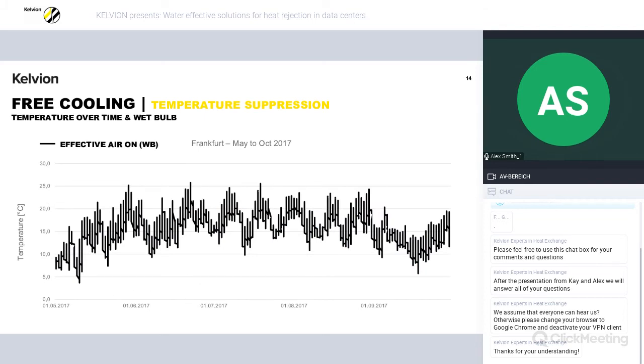If we're able to reduce the air temperature exactly to the wet bulb, our temperature distribution for the same site would look like this. Our maximum temperature is now 25.4 degrees C, which allows us to select a more efficient design of unit and also increases the number of hours where our process temperature is above the effective air on temperature, thereby increasing the hours of free cooling.